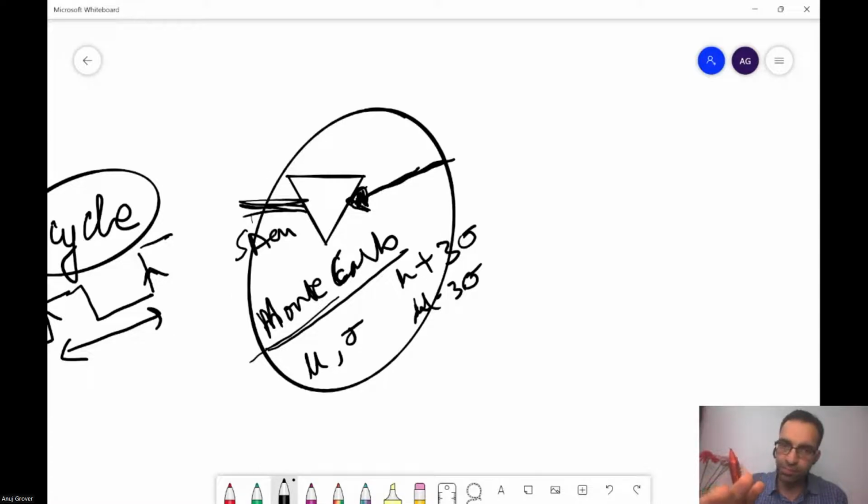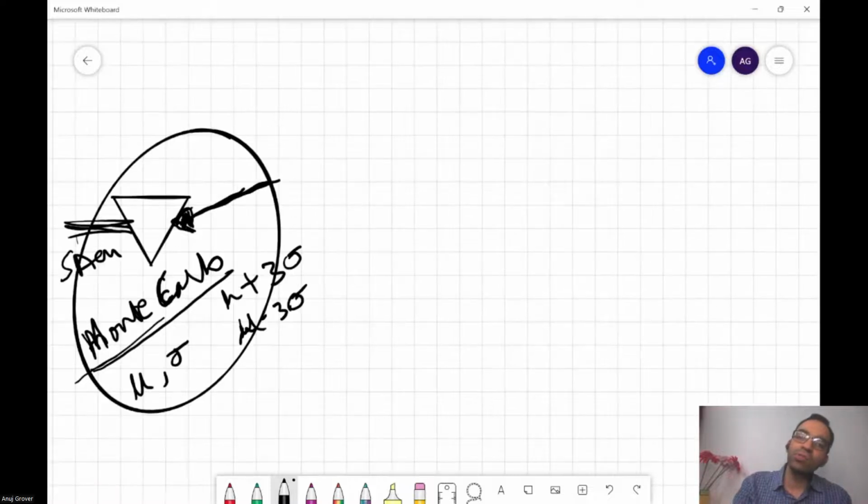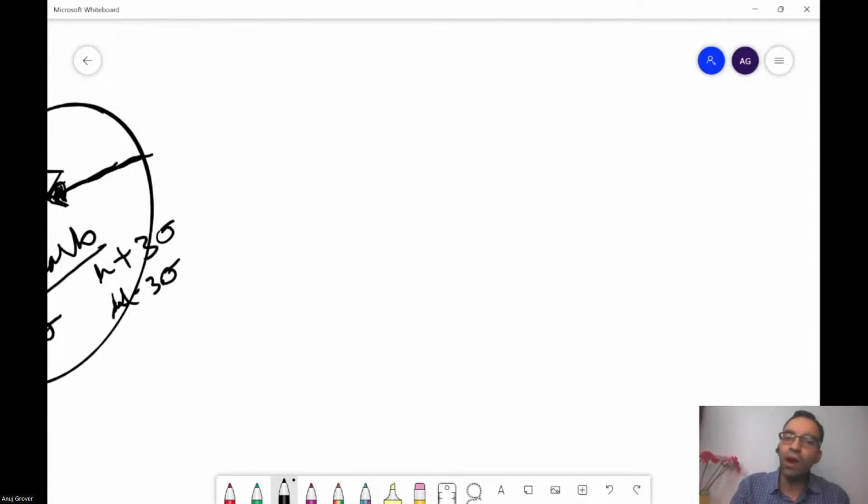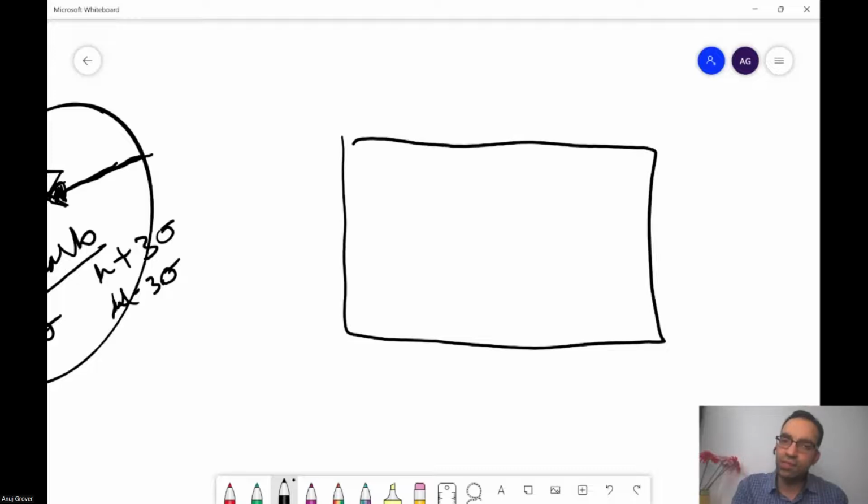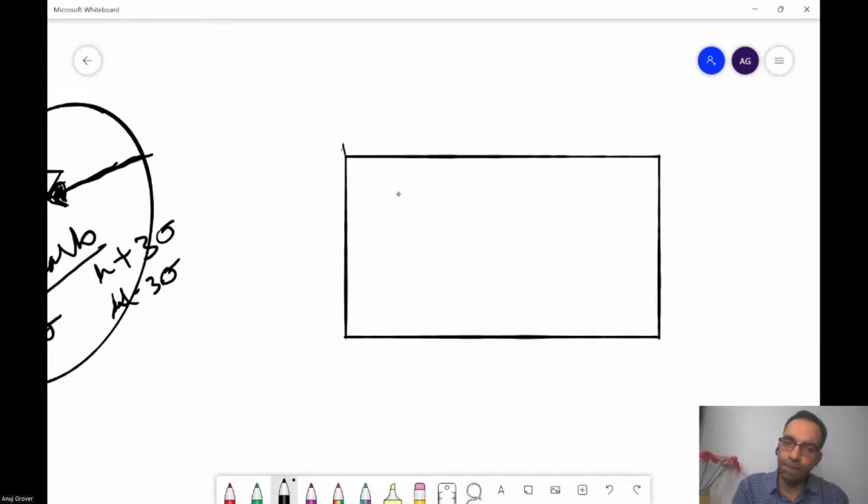Okay. Yes, sir. Now let's come to how we measure the offset, how I ensure that the offset my sense amplifier has when SAEN arrives is sufficient. For this, what we do is we actually make a critical path or a replica path. Where we make a dummy word line and dummy bit line.